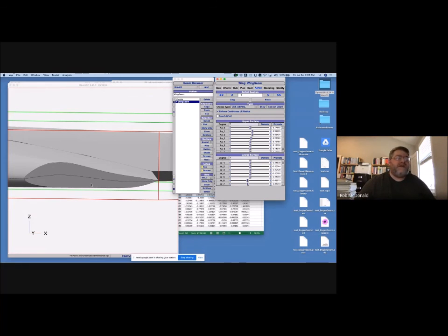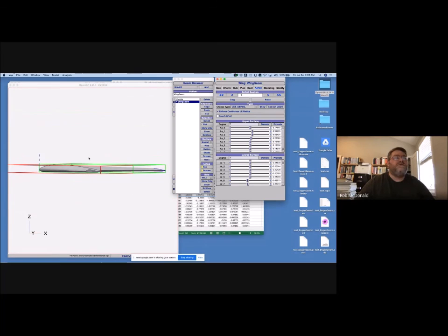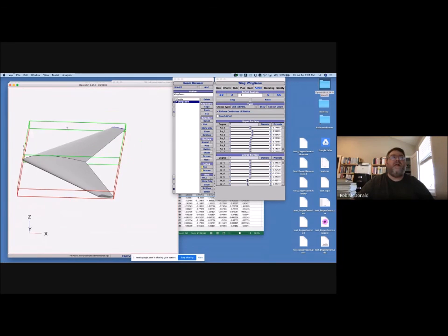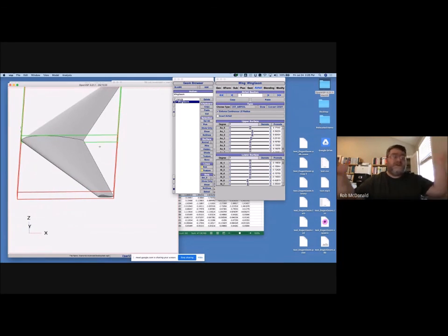So there's kind of two ways to make a flying wing or a blended wing body stable. You can use reflexed airfoils, where you have these airfoils that come back up in the back to counteract that moment and balance it out. Or you can use sweep and twist, or you can use a combination of them. They're not exclusive, they come together.